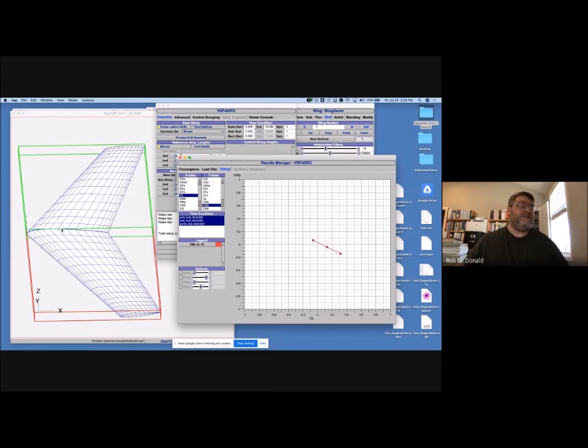So in order for the airplane to be trimmed, right, that moment, and now our moment center is our CG, right? Our moment about the CG needs to be 0. So for this airplane, we need to find where CMY is 0. So that comes to this line right here, right? That line. And then we look at where that line intersects, and that is at some CL, right?